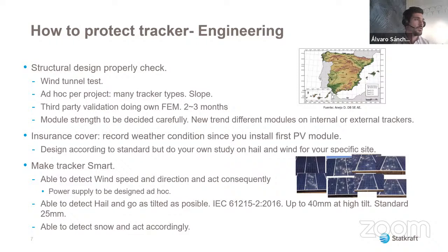Also, the last point regarding structural design check is the module strength. That has to be decided carefully, because now we are part of the IEC committee, and we know that there is a new trend among module suppliers, as they have to cut costs. One of the ways they are trying to cut costs is to make the same module, physically, but different in the loads it can withstand.